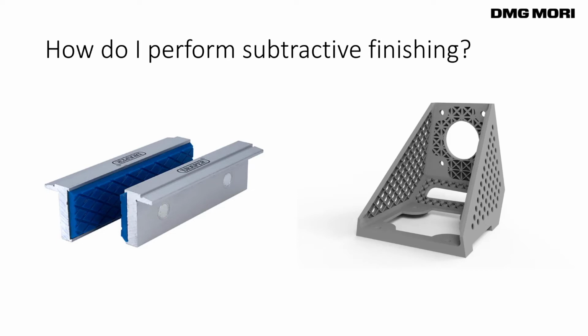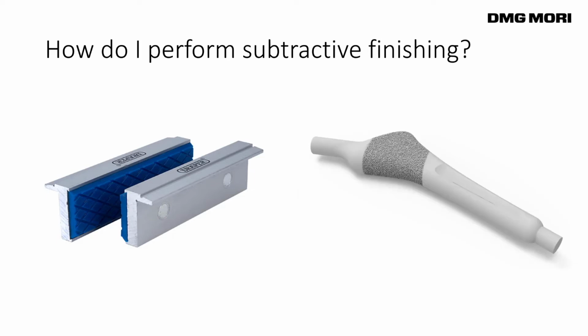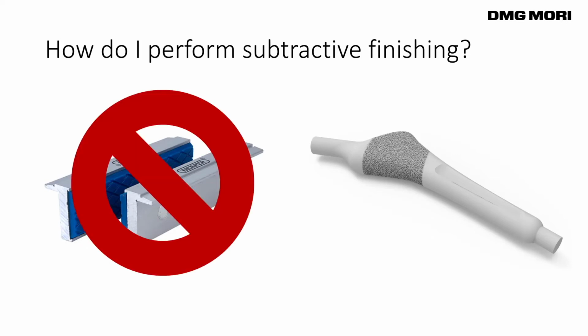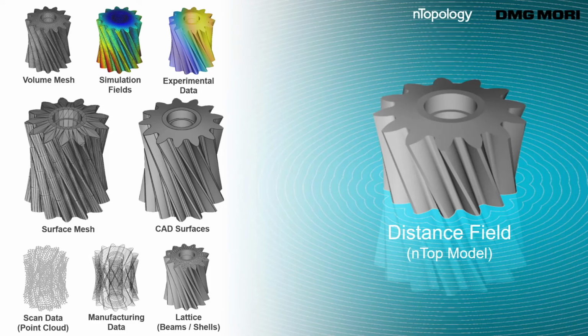So for some relatively simple geometry, like you see on the right-hand side, right, it's fairly easy to put those into soft jaws. But as we start looking at something like a femoral stem, it's not so straightforward how to go through the design process of creating soft jaws for something like that, right? We can't just clamp this part together. We have a very delicate region with a trabecular lattice structure. We can't just force that together and start crumpling some of the beams in our structure there.